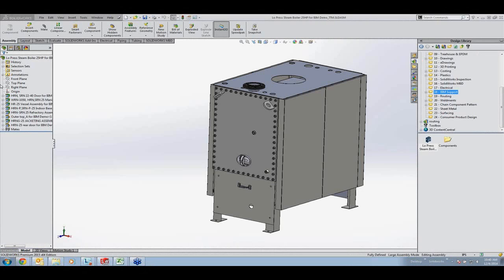You can also create a gusset with a flat sheet metal. It's not sheet metal, but in this case, just a flat bracket here and a tube. And even though there's a gap there with a round corner, like a fillet there, it'll still make the gusset just fine. You can make a gusset between two round members. And in this case, orientation is subjective because I don't have a flat face that has a normal orientation. In this case, it's a round, so normal is subjective. So I can go ahead and change that as I like. That looks good to me here.